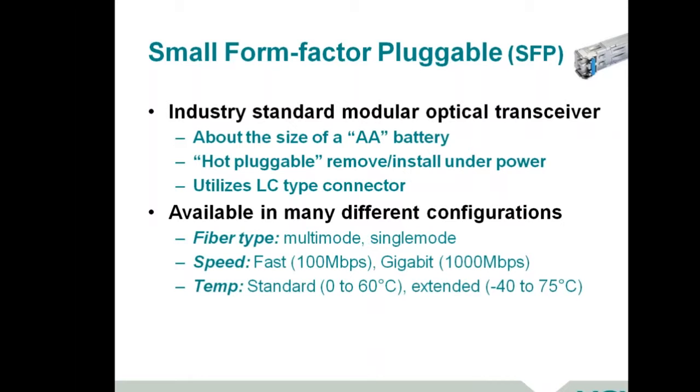And it does utilize the LC type connector, again important to understand when you're looking at this. It really gives you the best of both worlds in terms of flexibility. So you can choose single mode or multi-mode by the fiber and module that you choose, and be able to pick speeds as well as the operating temperature that you want.